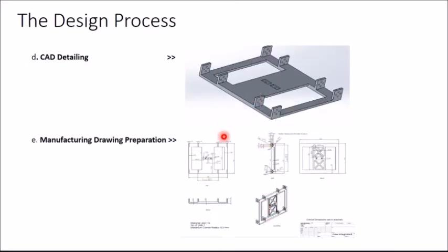Once this is done, the next step is to go for CAD modeling. Here you will be able to use your skills in SolidWorks for designing the part. Always make sure that the part assembles correctly with the rest of the system. One way to do this efficiently is to use inbuilt tools in SolidWorks like clearance verification, interference detection, and hole alignment. You can find more about these features over the internet.